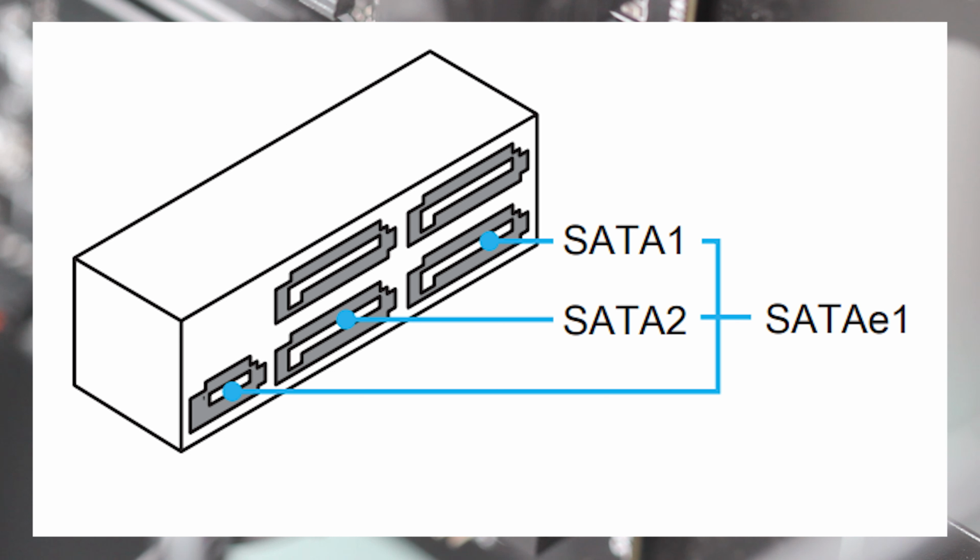All motherboards will be different, and using certain ports may disable other features. If you are only using a single storage device, then you don't really need to worry. But if you plan on adding additional storage devices later on, then you should check to make sure you are not disabling a feature that you may need later. It's not the end of the world, but getting to these cables later on can also be difficult.